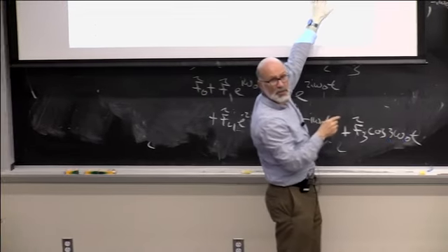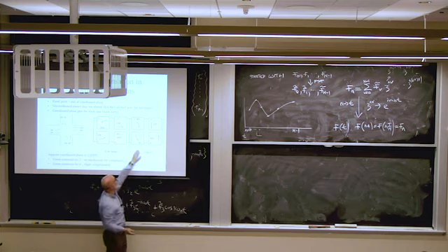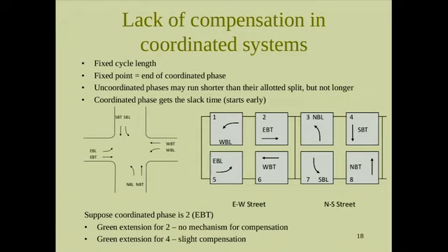These phases can have some actuation. They can have some detectors. And so they might run shorter than scheduled. And if they gap out quicker, run short, and this one gaps out, it runs short, that means 2 and 6 are going to start early. But if they start early, they never end early. They run their full length because that's how we have the full cycle.